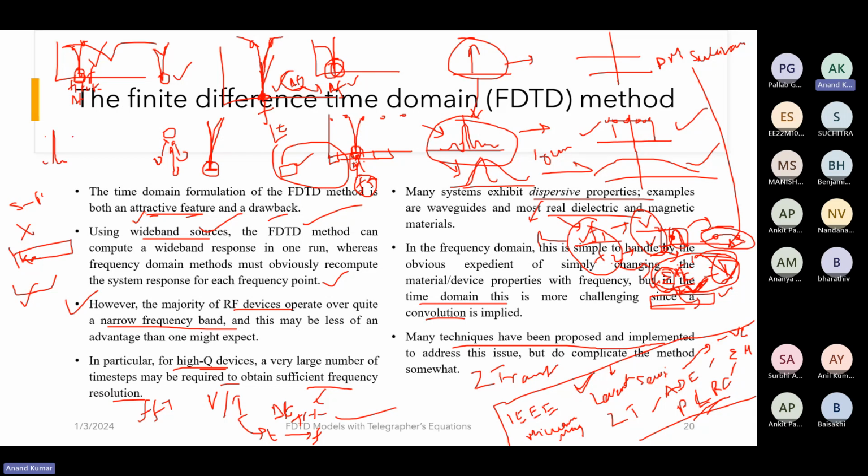or a sinc function. Your code will be dependent upon some delta t, and this delta t will actually help you resolve the frequency resolution, which is delta f. So this delta f will be determined by the time step which you choose for your simulation. If you did not choose this delta t correctly, this delta f won't be sufficient to catch this particular resonance. So you might end up with just this particular S parameter instead of getting the dip at the right place. So what I was trying to say is, you have to choose delta t small enough that you catch this particular resonance.